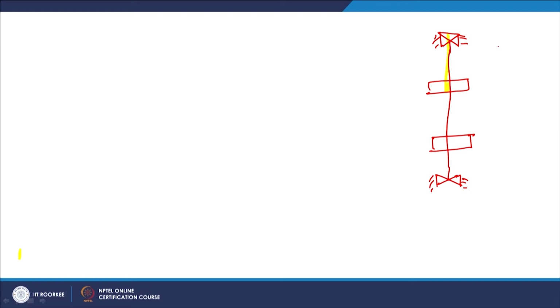Now suppose this shaft is vibrating, so we have this configuration. And this is the position of our rotors. So we assume that the shaft is light, and the rotors have some eccentricity between their geometric axis and the center of mass. So here we have, let's say, this G of the first rotor, and here is the G, the center of mass of the second rotor. So this is y1, this is y2, and here it is E1, and this is E2.